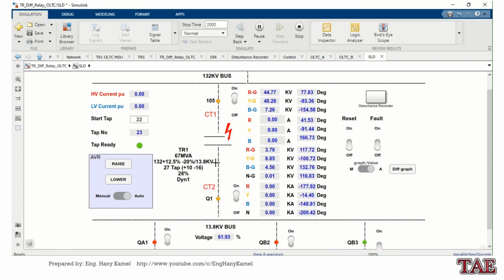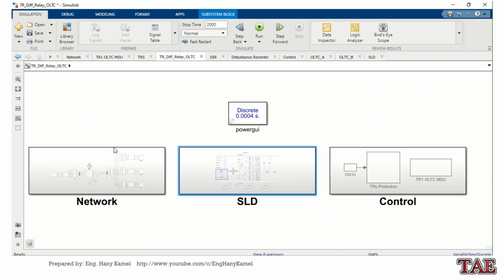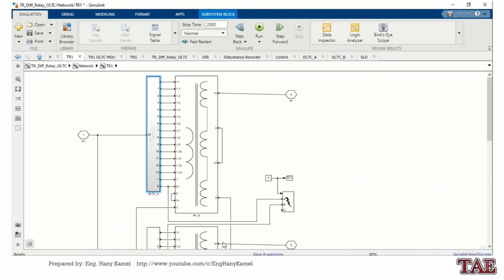So at some value of load, if there is any problem in the transition resistor, the current can increase past the limit for the differential relay and can give trip to protect the transformer. We'll normalize again.